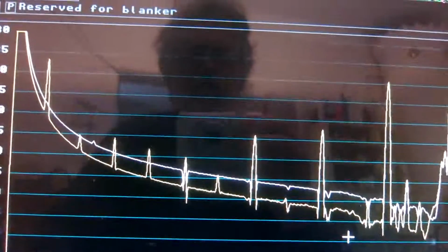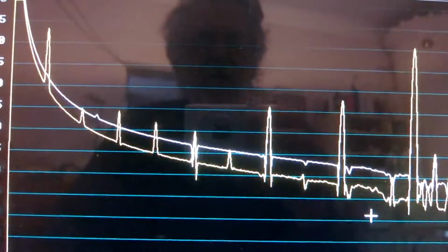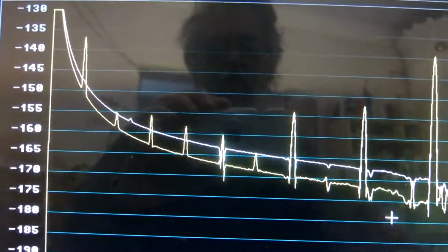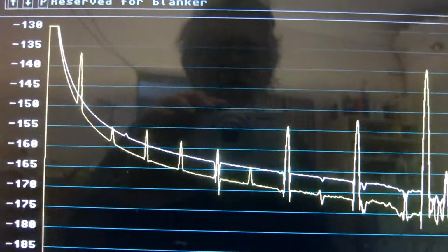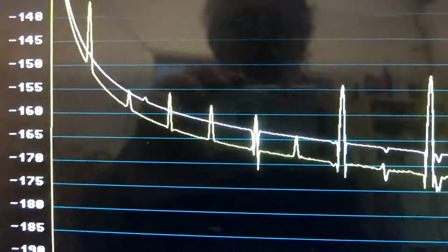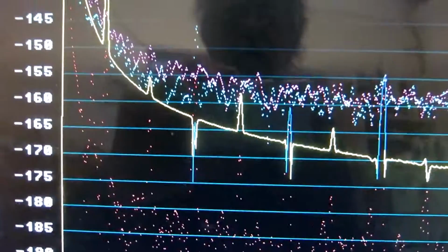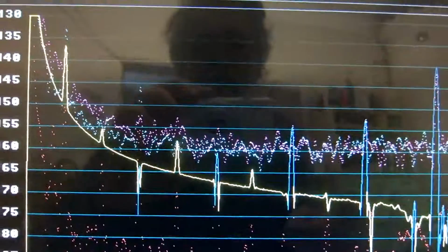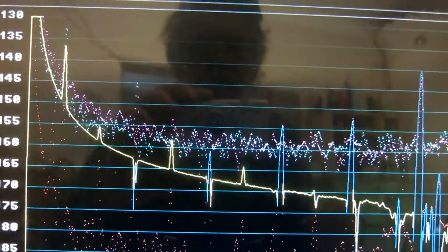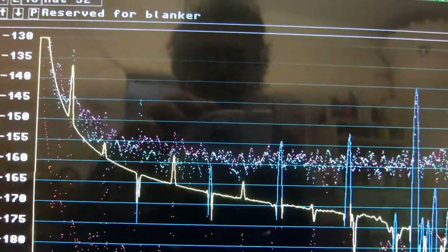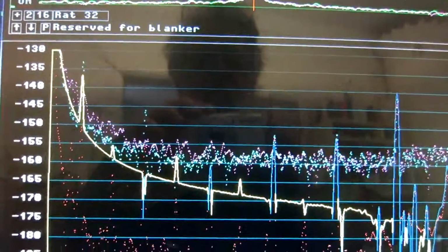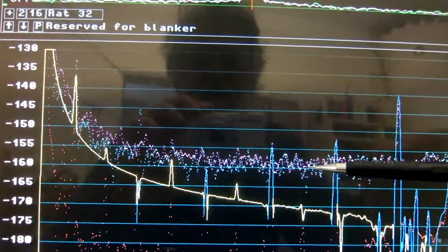These curves show the sum of the squares of the real part and the imaginary part of the correlation spectrum. Now, that is not quite what one should show, but it could be safe to show it. So I click now in this box here to show for the phase noise here. This is a little bit unstable. That is the raw data into the correlator. That is the detected FM signal, which then is used to compute correlation between the green and the red trace.